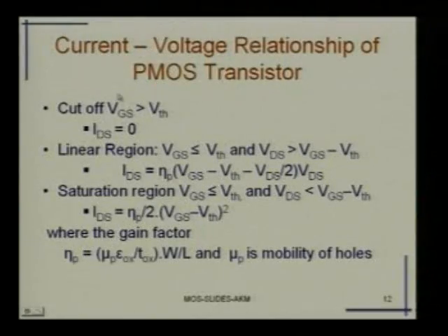So therefore VGS must be negative, and not merely negative, it should be less than the VTH, and if it is less than VTH, the current will flow, and this is the equation. Otherwise the equation structure is similar, analysis is almost the same.